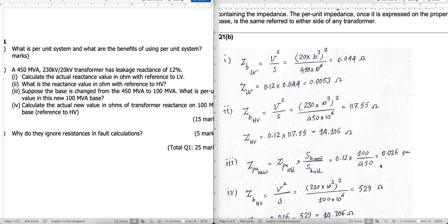Even if you skip this one, in the short circuit analysis, for that reactance diagram, again, you need the per unit. But there, except the transmission line, you just need to transit from an old per unit system to a new one. But here it is more focused on converting the ohmic impedances to per unit. It's more on the definition of per unit, except this section 3. You see, section 3 is transformation. So this is transformation from an old per unit system to a new one.